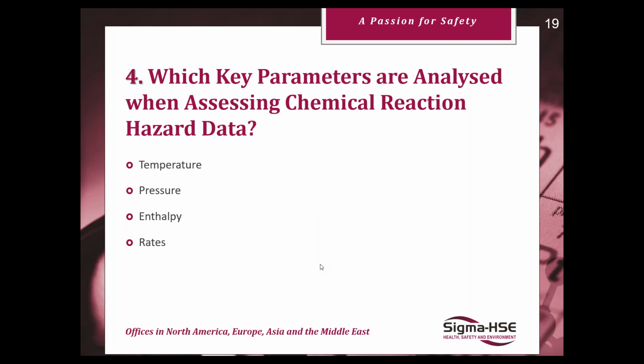So a lot of this is absolutely critical for assessing vent sizing requirements for reactors. But also if you are producing a gas, whether it be from your desired reaction or unintended reaction, what is the nature of that gas? Is it toxic? Has it got some other kind of health hazard to it? Are you going to need to scrub that gas? What kind of capacity do you need to be able to do that safely and properly?